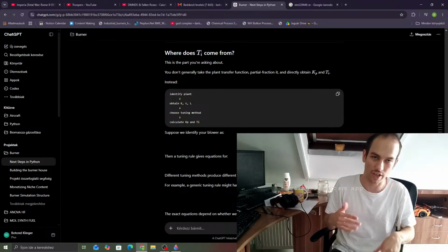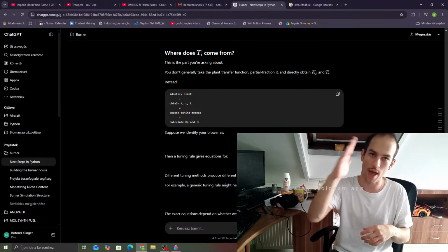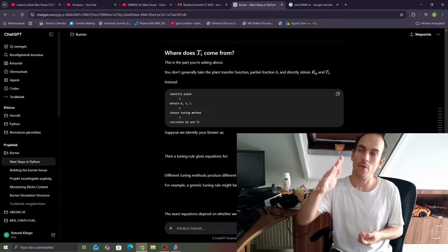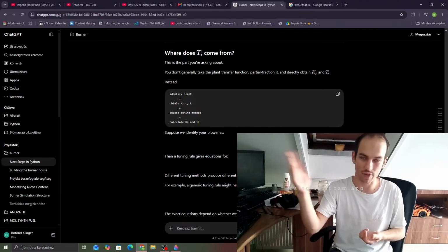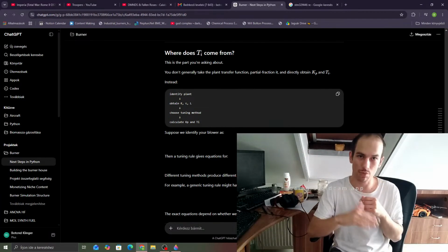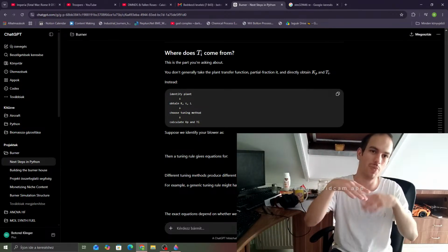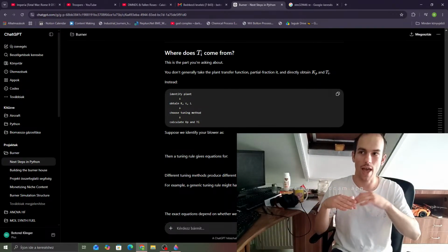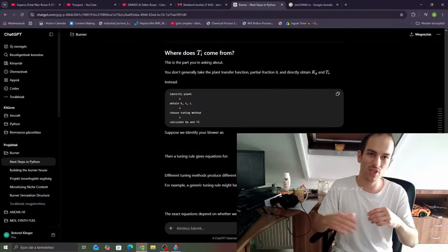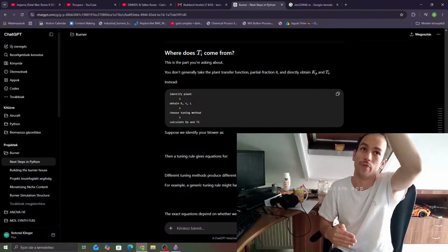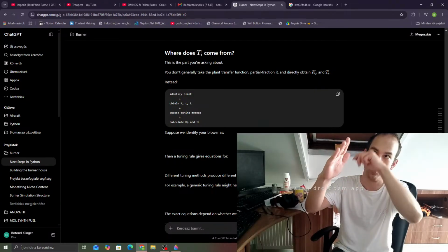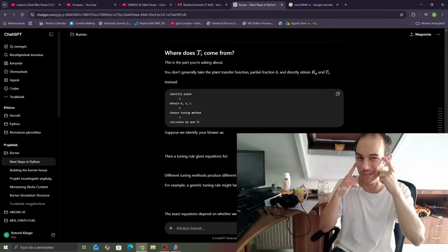And there is also the derivative. You have a function, in terms of the response, that has some sort of steepness. The steeper it is, the bigger the derivative gain is. So if you start increasing the PWM from 20 to 70%, the output will shoot way up. Then the derivative will take that as a very big change, so it will counteract that. That's why the negative